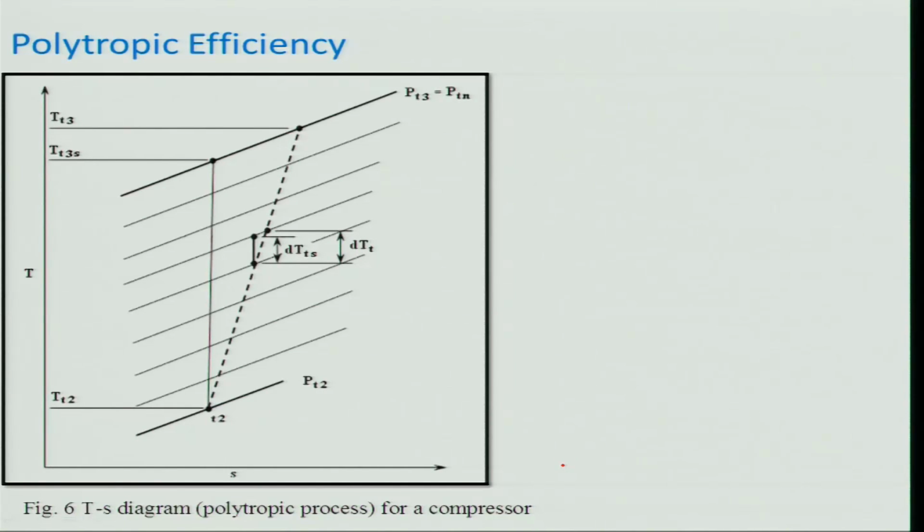That means there are several stages, right, and whether we can assume this isentropic efficiency to be constant for such a high pressure ratio or not. You will be surprised to know that it is not prudent to use a constant isentropic efficiency across all stages of a modern axial compressor, particularly with more stages.